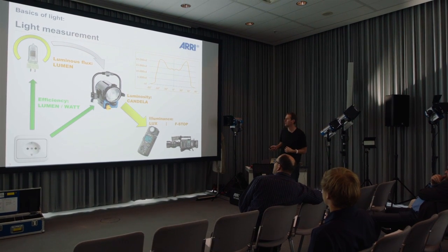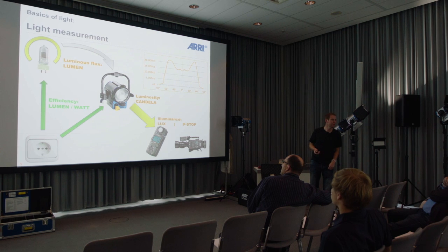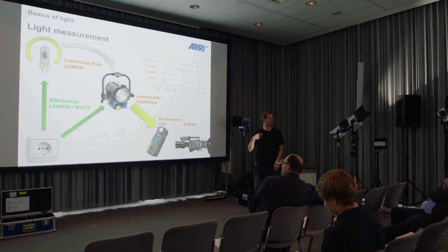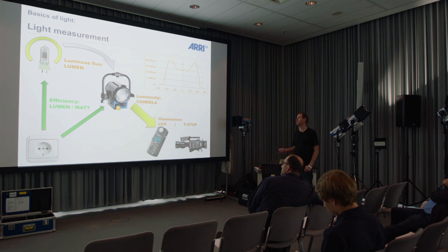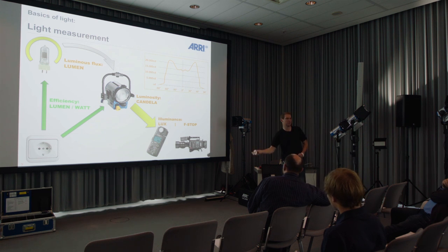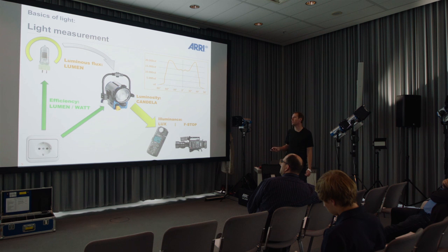If you only look at the candela, it doesn't give you all the information that you need to judge the fixture. Last thing, especially if we talk about LED, one main advantage of LED is that they are very efficient. Efficient, or efficiency, what does it mean? Very simple. How much light do I get for the electric power I put inside the fixture? That is efficiency, and it's measured in lumen per watt. So in the next slides, you will often see a value for lumen per watt, and this tells you how efficient this technology works.